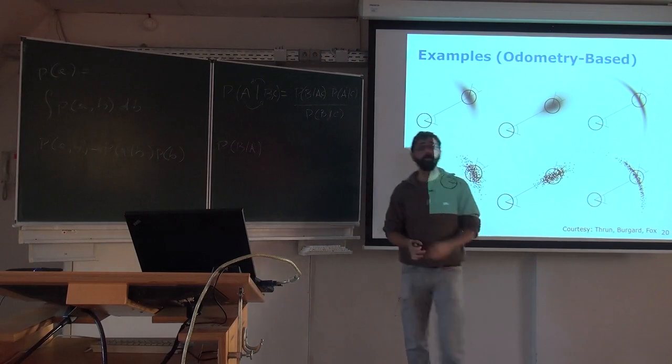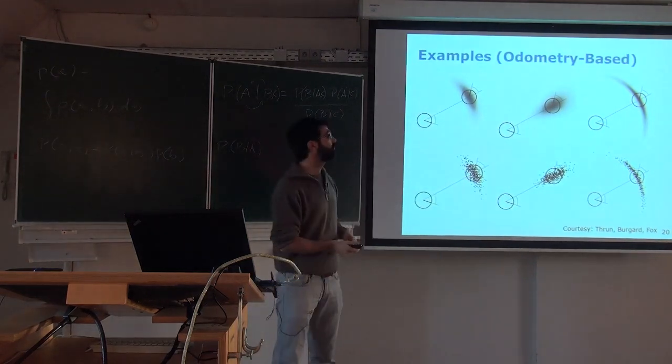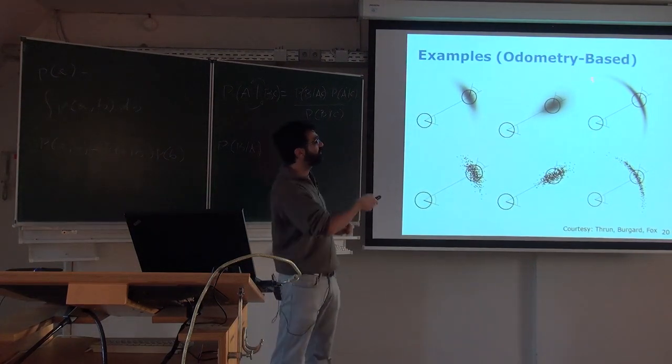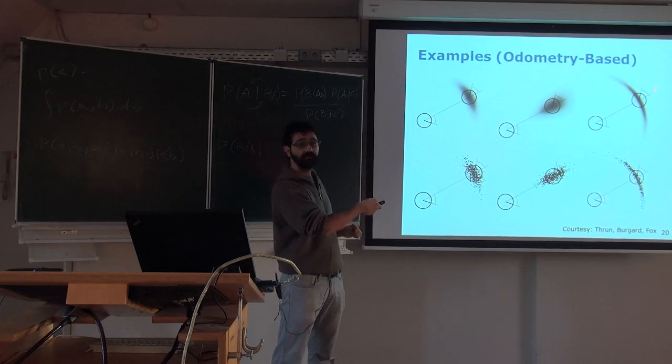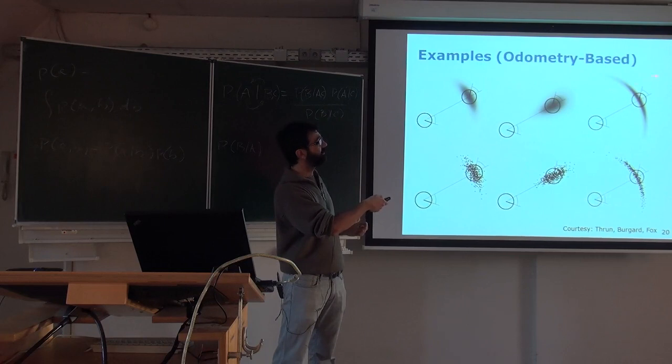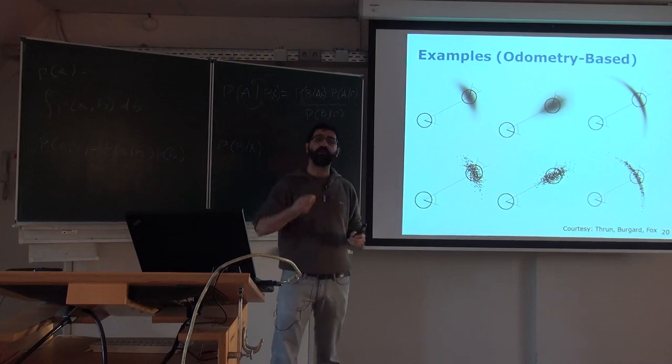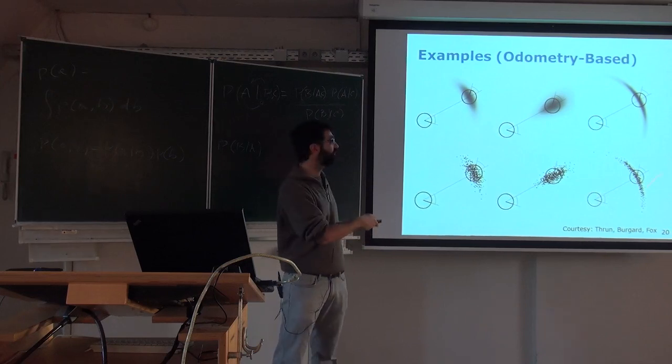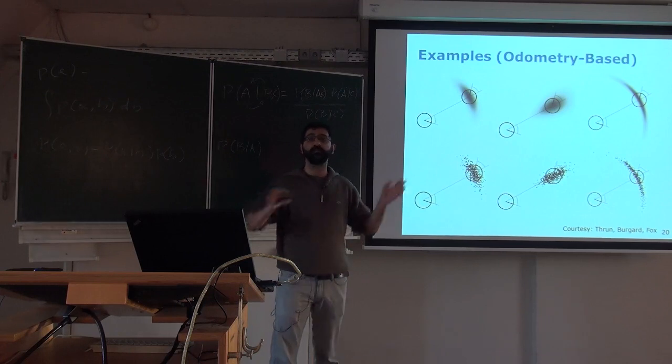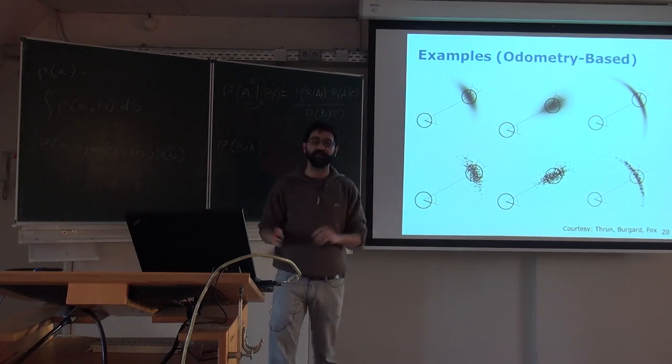So basically, if you want to do, let's say, a dense distribution, here is a grid with different values, and you want to know the probability of the robot being somewhere, you just take an area and you sum these values up. And in this case, you just do the same, but you have just a different set of things to measure. Here are more continuous, and here are discretized. Okay? According to the application, one is better than the other.